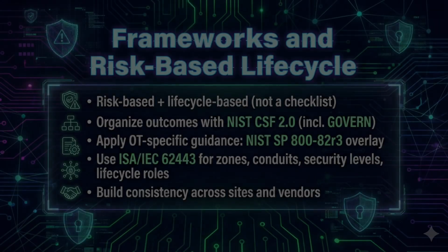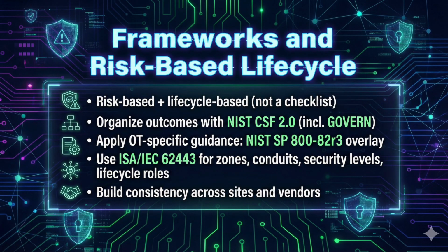Now we organize the work. A best practice program is risk-based and lifecycle-based. Risk-based means we don't apply controls as a checklist. We tailor them to the process criticality, safety hazards, and business impact. Lifecycle-based means we plan security from design through operations, not as a bolt-on after commissioning.